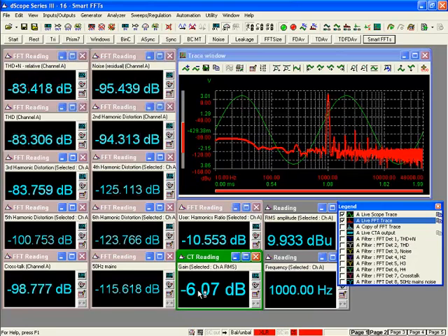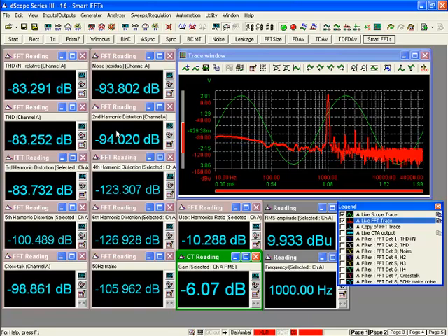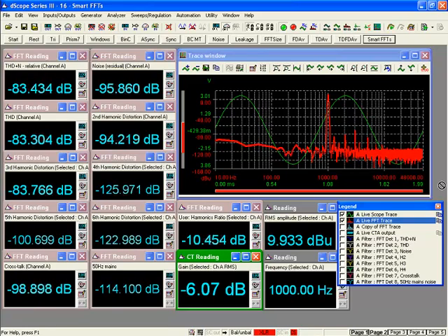So this is just one snapshot of the kind of thing that you might do when you've first built your prototype or received your first samples from your supplier and you're wanting to analyze many of these parameters. This can all be done in real time from an FFT, and these are all updating live, so if I now go to refine my circuit design in any way, I will see how all of these parameters update, and I can track the trade-off from one parameter to the next as I tweak my circuit design. So this is just one illustration of the power of FFT processing and what it can do for you in terms of increasing the speed of your workflow when you're doing this kind of measurement.